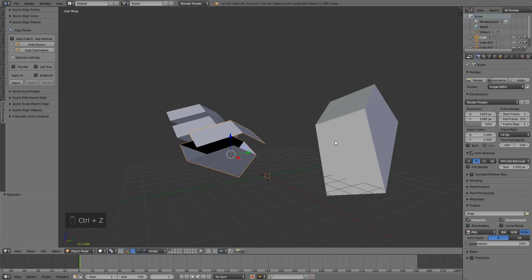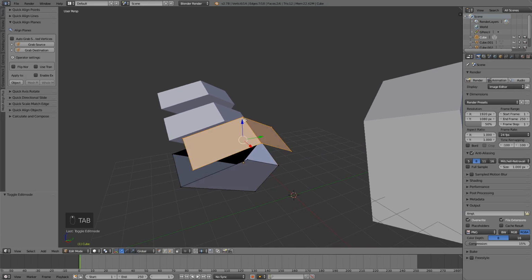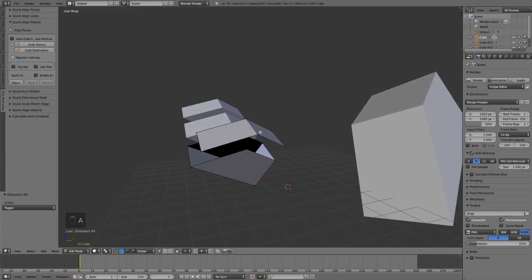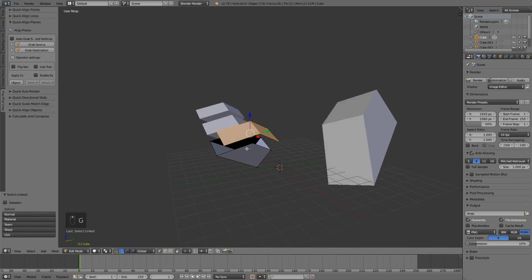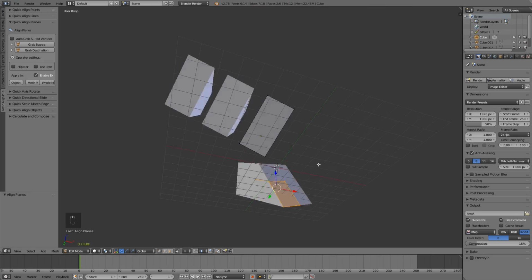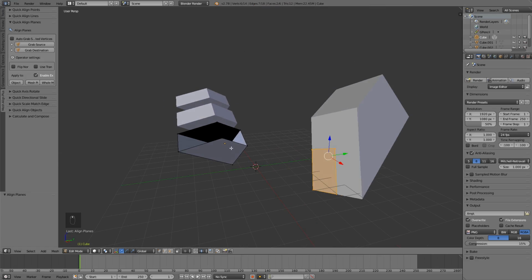So we already defined a destination earlier, so I'm going to leave that the same. It's going to be these 3 verts over here. But the source is going to be a little different. So we're going to pick 3 verts as normal by hitting Grab Source with those selected. But now we're going to instead select whatever we want to move in edit mode. So we're going to select these verts, and then we're going to make sure this is checked and hit Apply to Mesh Piece. And that's going to move only the selected verts in edit mode. And this is useful during the modeling process while you're constructing a model.